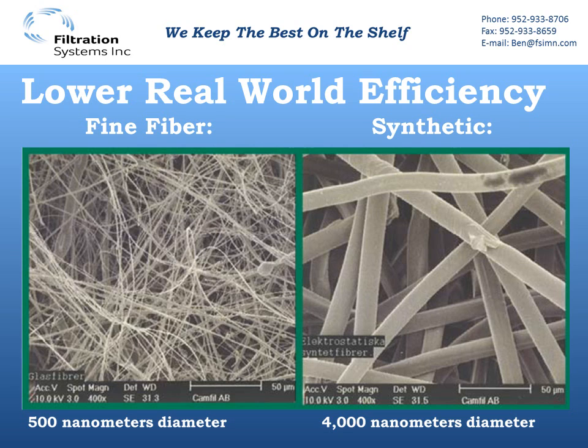Well, that's not the case in high-efficiency filters because the size of the particles that we're taking out of the air are so small that they simply cannot add up to a large enough mass to aid in the straining effect of the filters, especially when the gaps between the fibers are as large as they are in modern synthetic medias.